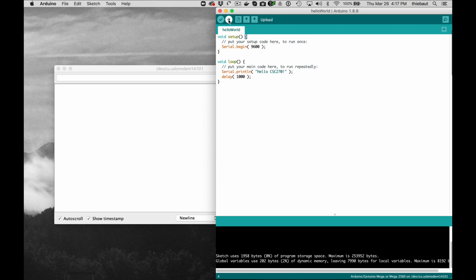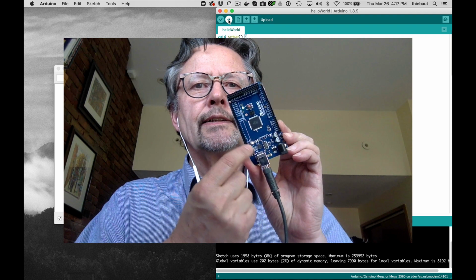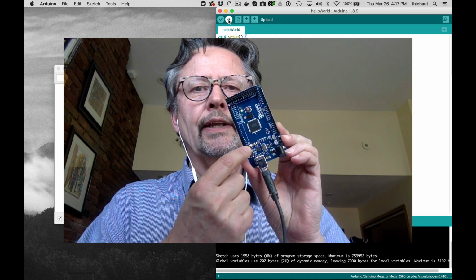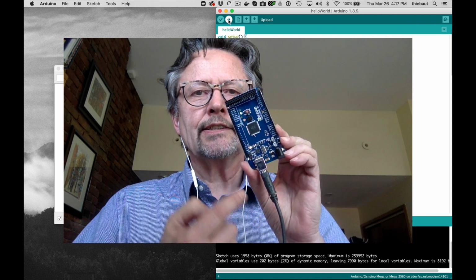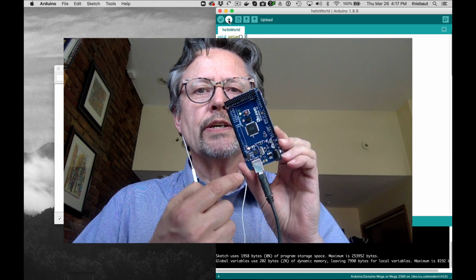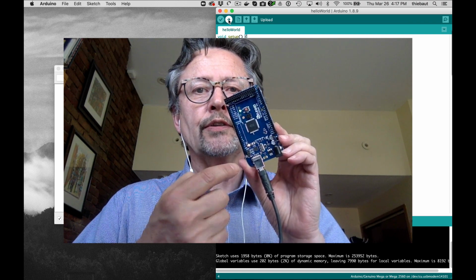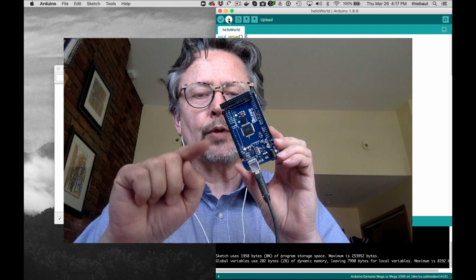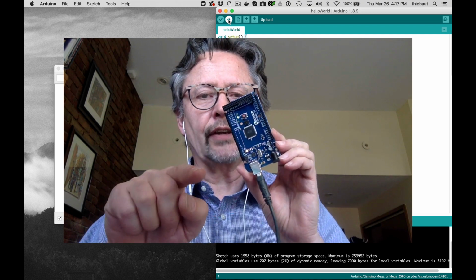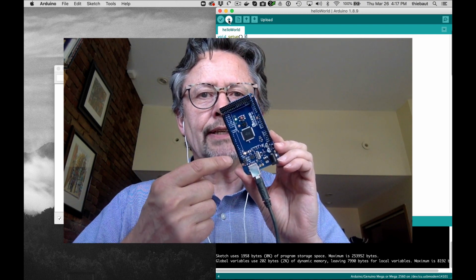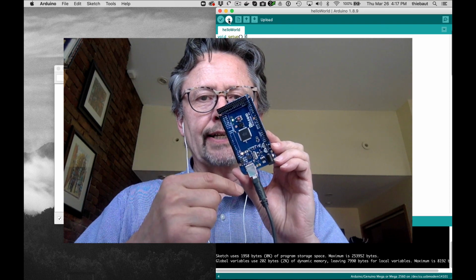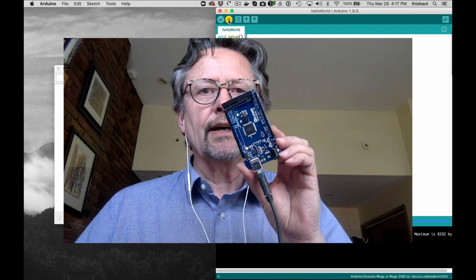I'm going to put it right there, so you're going to see that something should happen around here, some blinking. That blinking is all the bytes of the opcode from the program that has been compiled coming in, and the Arduino will respond saying, okay, I got it. So there will be two LEDs.